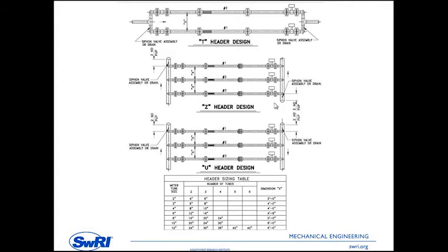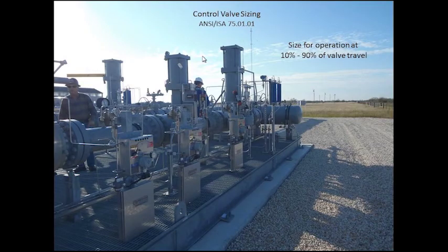One thing I want to point out, this is an important little consideration. This note, 2 nominal pipe diameters between the T and the end cap on this header. If you don't have that opportunity there to move that turbulent junction of the end cap away from that T, you'll find that your runs 2 and 3 will have greater flow than the primary run.